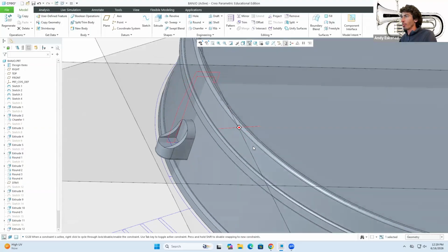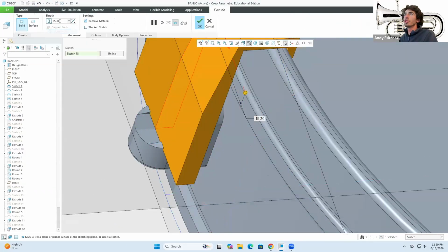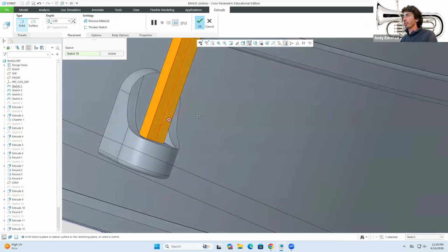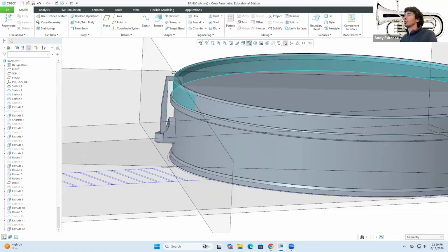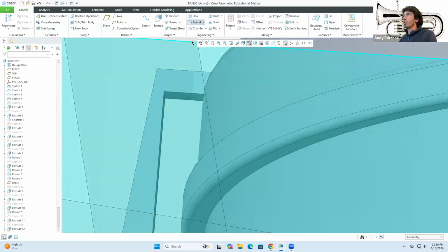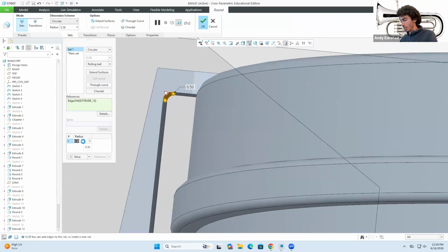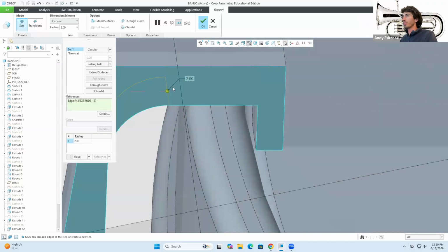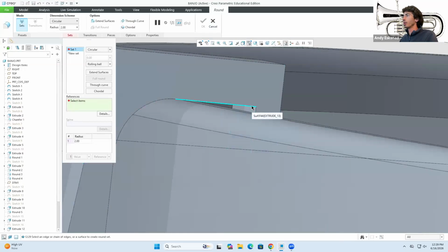Okay, so we have our overall base figure in here. So I'll go over to extrude, symmetric. Well, not 1, let's do 2. Then we have our figure in there. Excellent. So now let's come over to round. First things first, let's round that appropriately to do a 2. Let's do the same thing over here.